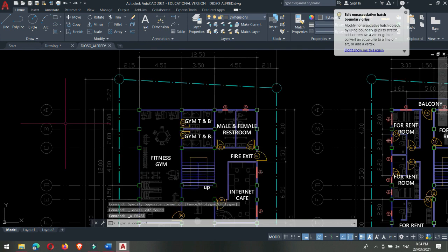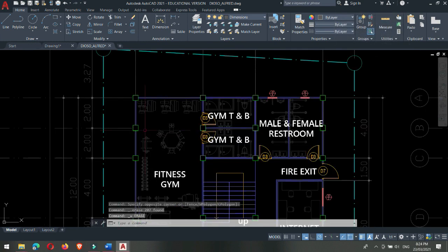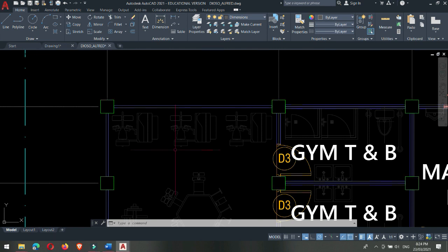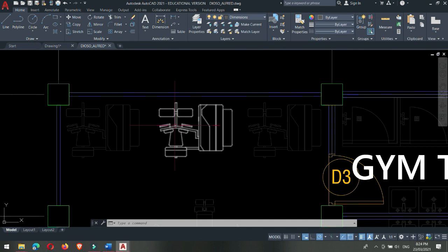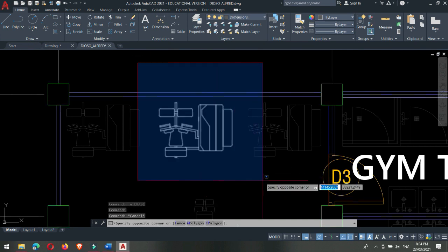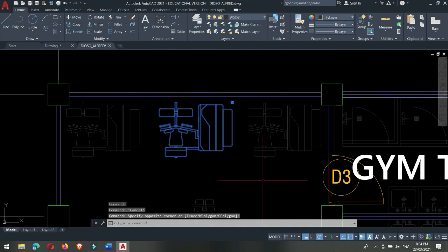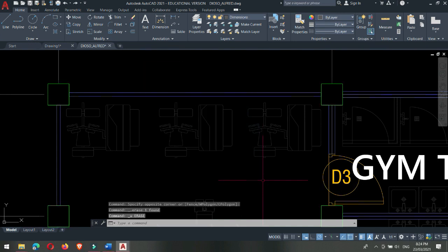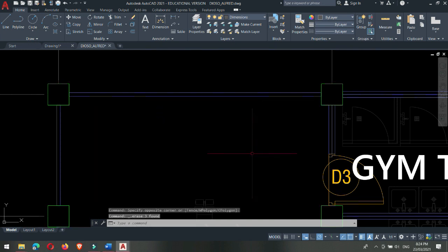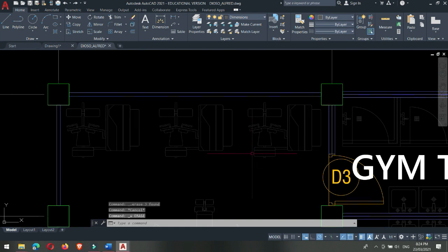all disappear. But if I want to use the second method, I use it when I want to select something very specific without touching some entities inside AutoCAD to make it fast. Example, I'm going to click this one, so left click here, and even though it touches some boundaries, it is not selected. I'm going to delete this one, Control Z. But you also can left click and delete, Control Z. So there's a lot of ways to do that. It's for you how to maximize it.